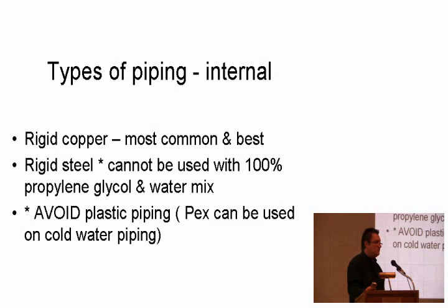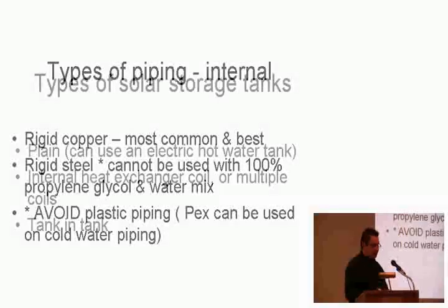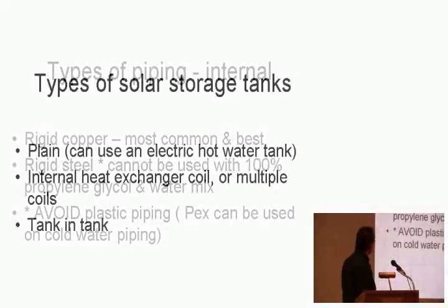I know some manufacturers will say that after 6 feet from the collectors or what have you, you can use it. I've done testing with it, and the fittings keep loosening off all the time because of the different rates of thermal expansion with metal versus plastic, and the things continuously leak and just tons of problems with plastic. Next slide.